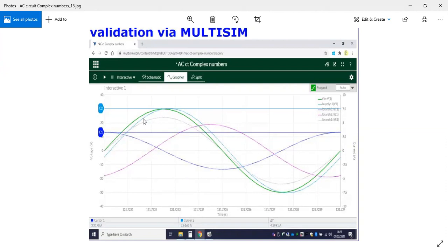The supply current is the dotted blue line here, with cursors put onto the peak of the supply current. We get a value down here of 7.61, which matches up very closely to our calculation of 7.59. Why would there be a slight discrepancy of 0.02? Well, 2 reasons. One is the eyesight as to where you exactly put the cursor on top of the waveform, and also the number of decimal points we're using in our calculation.